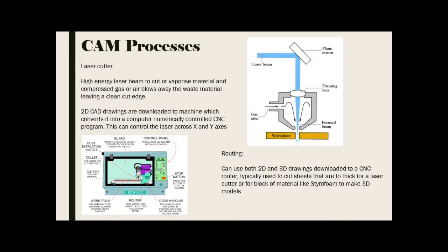When you're cutting, think of the thickness of a bandsaw blade or a circular saw blade or a tenon saw blade, that is a couple of millimetres thick, so you have to factor that in when you're making your product or whatever it is you're doing. But with the laser cutter, the laser line is very, very thin, so it can be highly accurate.